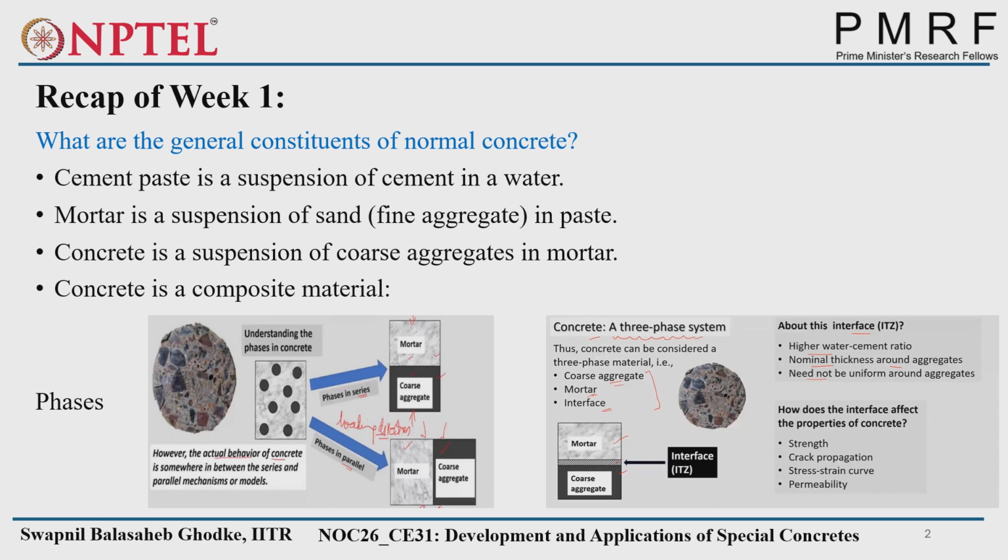As a quartz powder. Quartz powder will be costly, and ultra high performance concrete is also very costly as compared to normal concrete. Super plasticizer is not that costly. If you see any type of admixtures, we are not using them in too much quantity. We are using only 0.5 to 1% of the binder content.